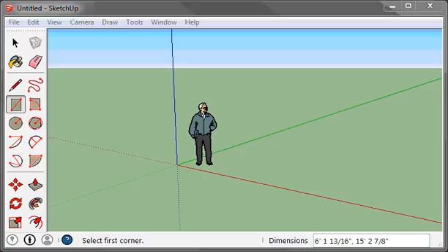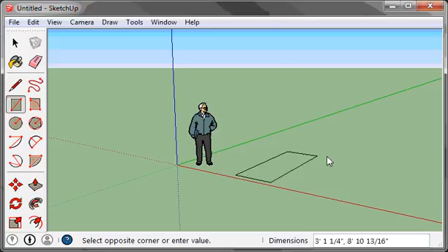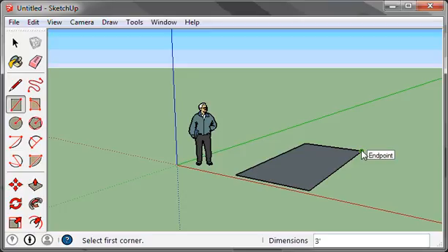After you've opened SketchUp and chosen the feet and inches template, use the rectangle tool to draw a simple table shape. I'll make ours 3 feet by 5 feet. And the way that you can choose this is by entering on the keyboard 3 apostrophe, comma, 5 apostrophe, and hitting enter. You don't have to click to begin typing, just hit the numbers you want.